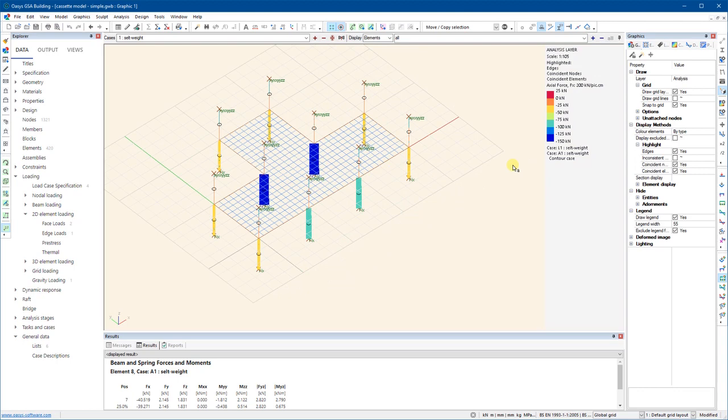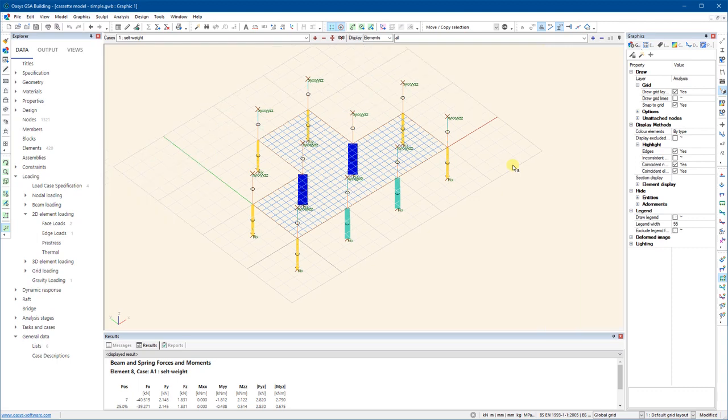If you press Control, Alt and L again, it sets the legend in its own bar at the side, and when you print it, that's not going to overlap with the diagram. And if you press Control, Alt and L again, it gets rid of it completely. So maybe you want that in terms of your diagramming. I would say that if you look for hotkeys in the GSA manual, it gives a whole list of these which you could find quite helpful.